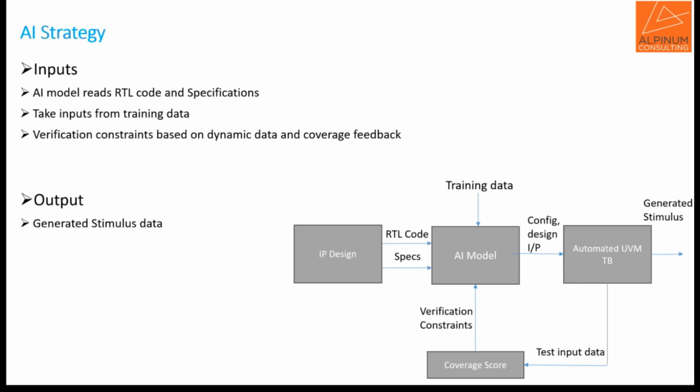This is the way we work it here: we take the IP design separately. Quite often, rather than using the actual IP design itself, now we're using configs, the specifications only, because obviously you don't really want to pull the RTL too much into your verification solution.